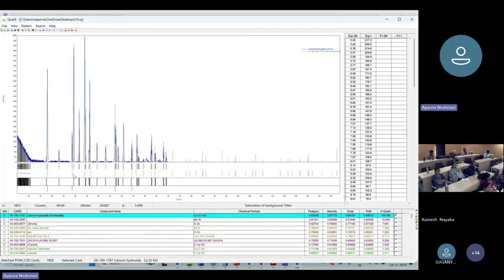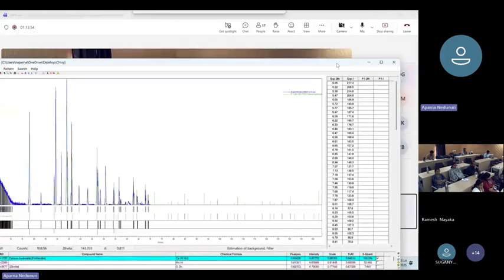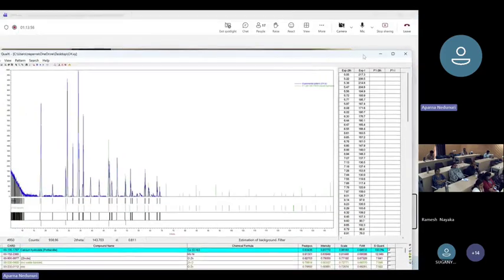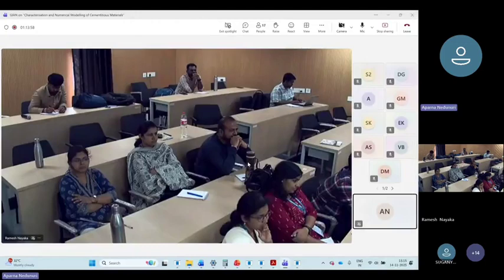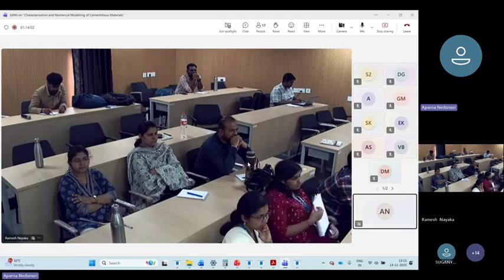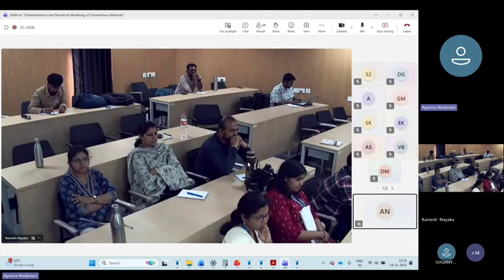Again, you have a Portlandite peak at this peak position. So this peak is Portlandite, but there is again another peak over here where the peak positions are not matching. Means the sample that I'm showing now is not a single phase sample. It may have some other material in it. That's why we have a lot of peaks which are not identified. We could only identify peaks of certain positions, right?